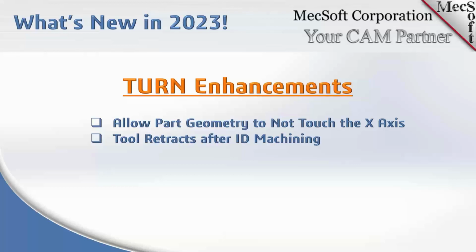If you don't have enough stock material behind the part, it made that impossible to do the cutoff, or difficult to do the part off operation in the back. Now your part can be offset out from the X-axis, and it'll automatically compensate for that when it defines the part geometry, which makes it a lot easier.